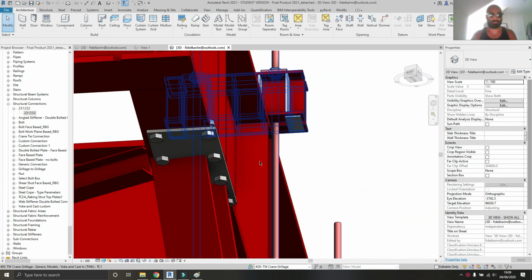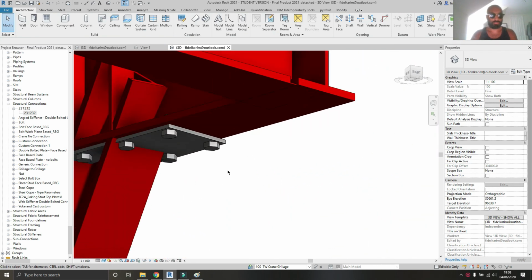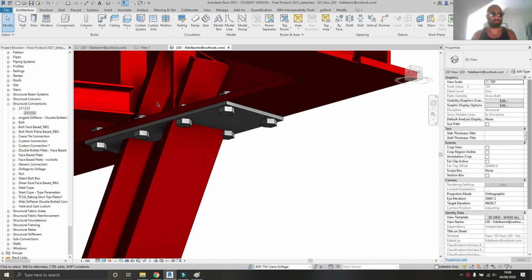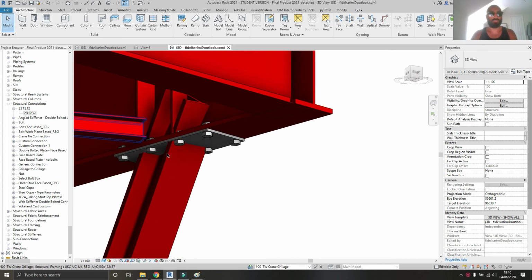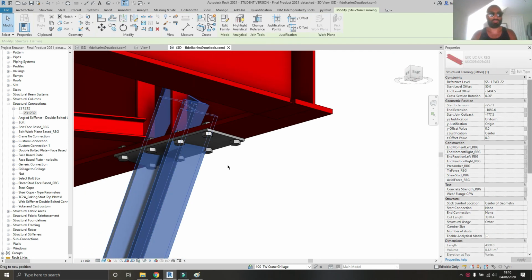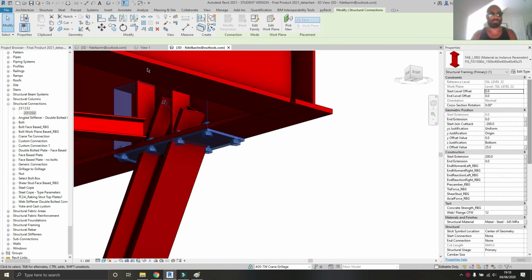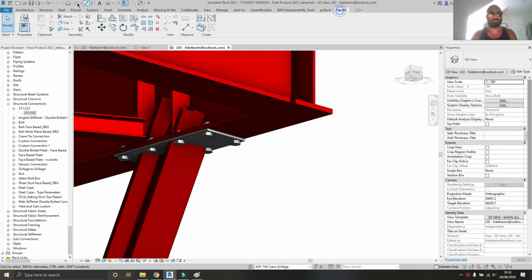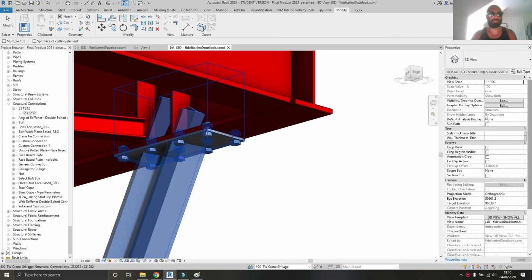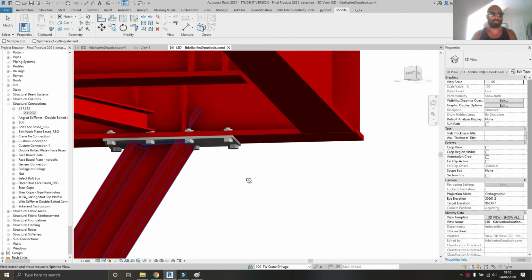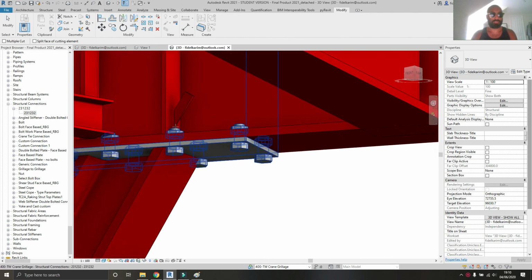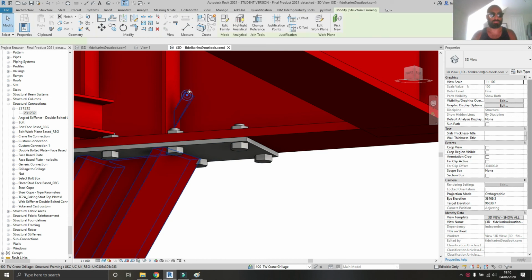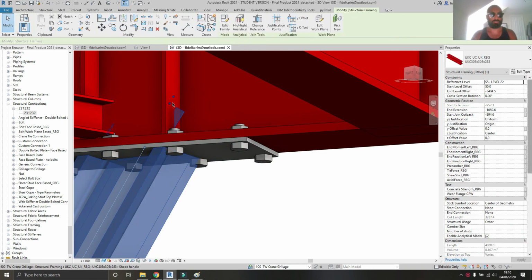Yeah, you can then place it and do all sorts with it. Of course, as I said, we need to be able to cut this. So drag it back to whichever position and select, come to modify, say cut this one with that one, and there you go. See, because it's at an angle, that issue has occurred. So what I will do in this particular case is just drag this one back.